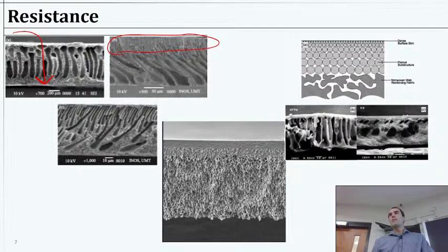Now, as we start talking about fouling in a moment, this little graphic up here shows a membrane where water could go through, but as you stack these little particles on, you might form what we call this cake layer of particles that water has to filter through even to reach the membrane. So it's almost like you're adding a membrane on top of the membrane if you get too much fouling going. So we generally want to try to remove that, even though maybe it helps us remove more particles from the water. It's at a cost of how much pressure, the energy to apply that pressure.